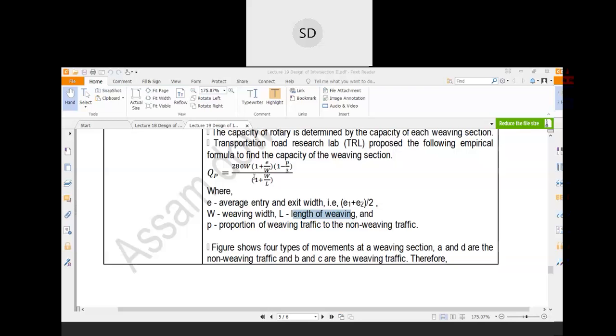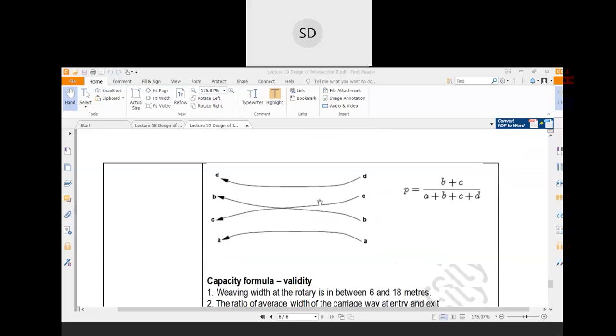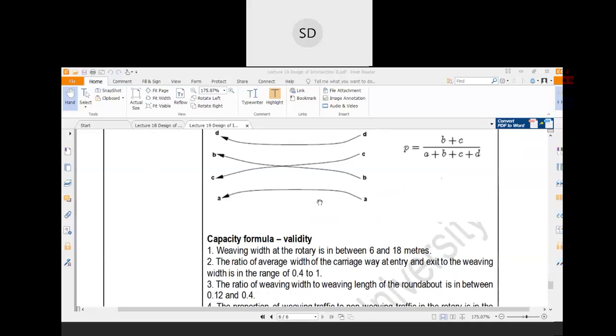So there would be traffic congestion in most cases, because the maximum capacity of a rotary intersection is 3000 vehicles per hour, but in the actual case it is exceeding the capacity. Therefore, in such cases you can suggest that the rotary intersection is not suitable, and we can go for a grade separated intersection. So basically this is the usefulness of this formula.